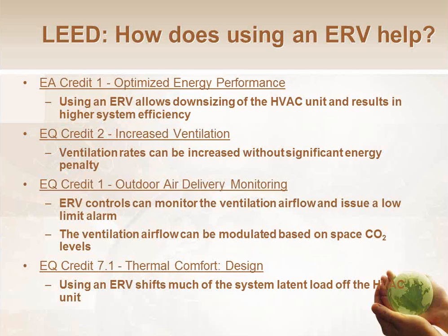If you choose to do the increased ventilation credit, EQ Credit 2, I'm not a fan of increasing the ventilation. In fact, I'm a fan of decreasing it below the code required amount with using CO2 sensors. But if you want to do that increased ventilation and increase your outside air by 30%, that's fine. There's health benefits perhaps to doing that. But when you choose to do that, you're going to use a lot more energy. So the ERV is a way to offset that energy and make it kind of an energy neutral penalty.